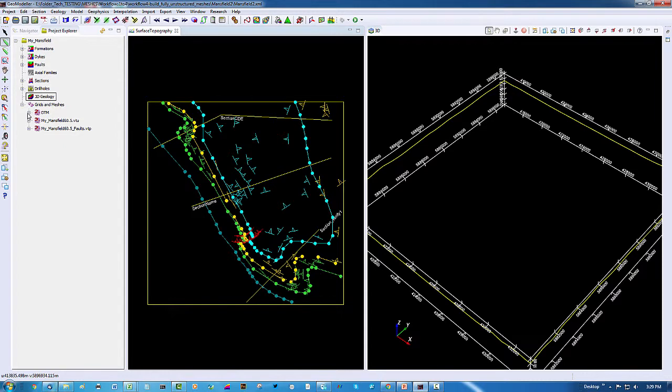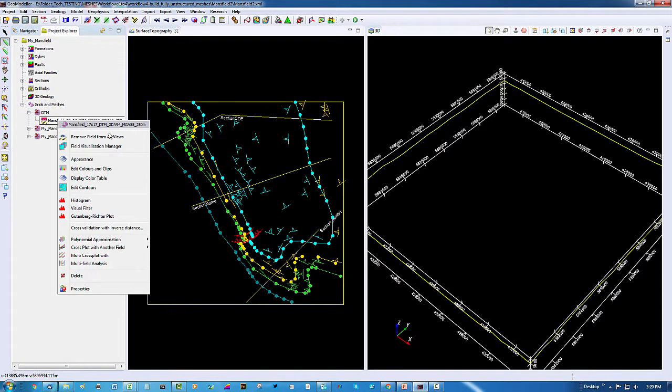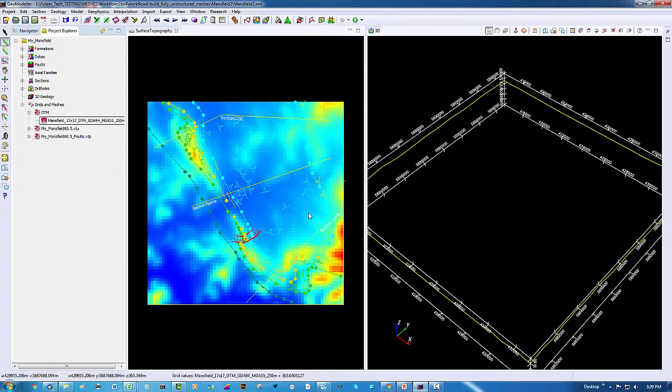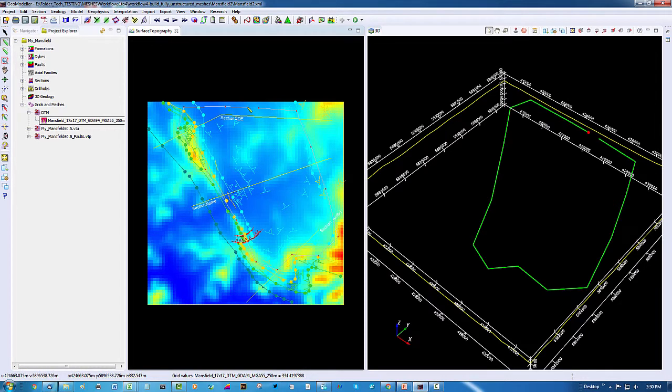We also need to show the digital terrain model because this will help to guide us around the watershed zone. I'm just approximating this to the ridges at the limbs of the syncline. You see it's following me now in the 3D viewer, and that's enough points.